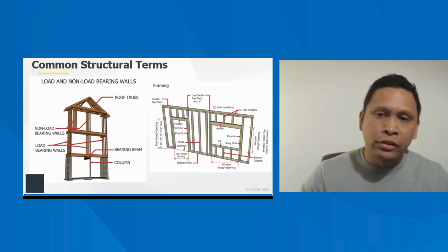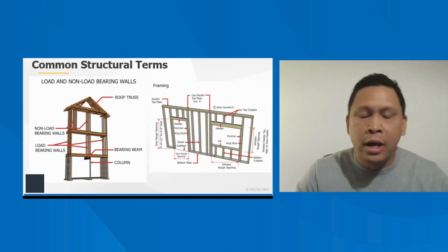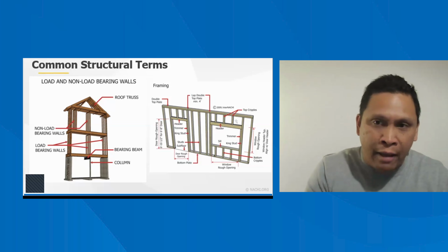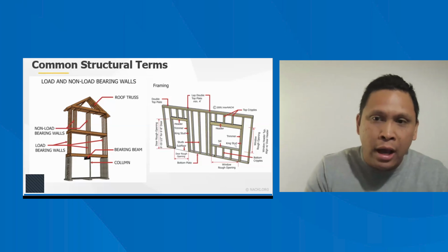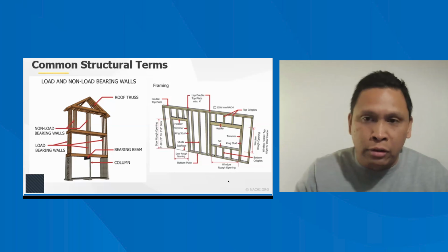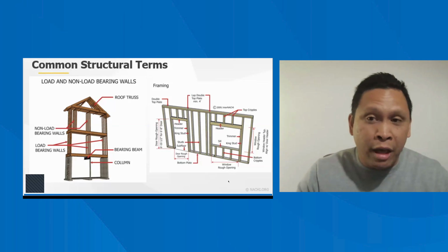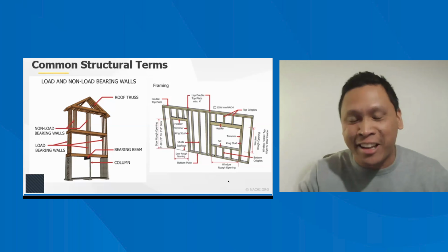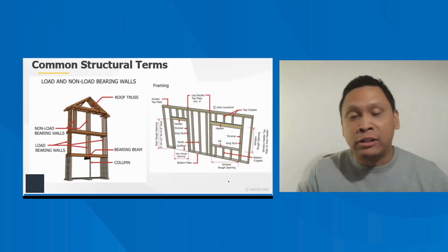So for those of you that are doing pre-drywall inspections on new construction, when you are looking at the king studs, when you're looking at the jack studs, remember, don't just look to make sure that they are in place. Also, make sure that they're actually cut long enough to be able to help create that continuous load path, and actually do what it's supposed to be doing.